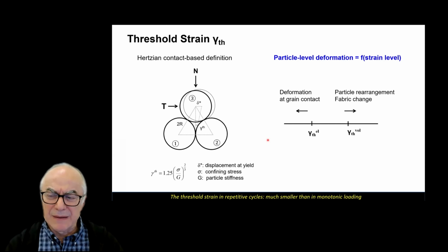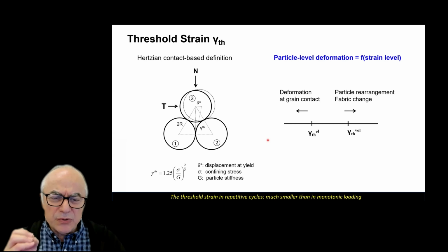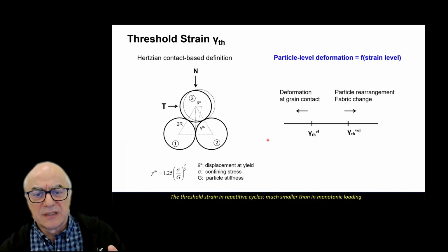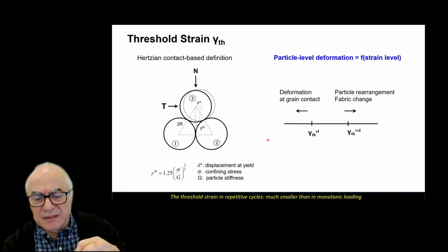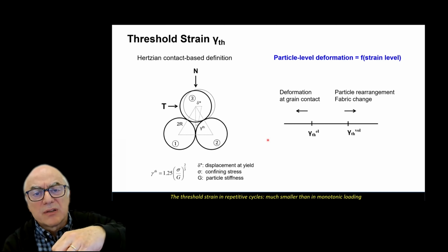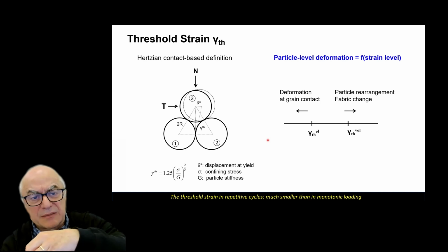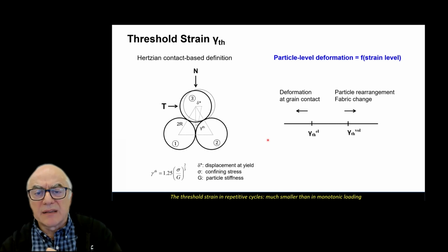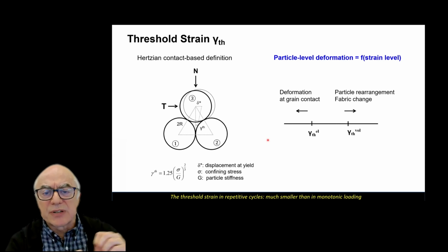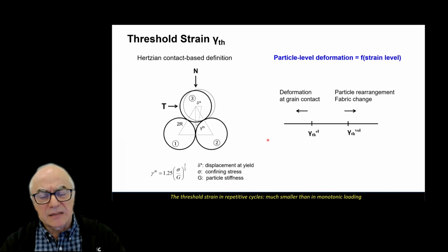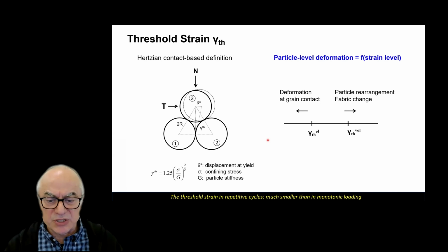on the material. It gets to a point that when you do the calculations, it appears that the relative displacement between 2 grains is smaller than 1 angstrom. And you say, well, but there has to be about 1 angstrom displacement in order to break bonds to cause frictional displacement, shear displacement. So what is actually taking place is not every particle moving relative to every particle. It appears that bunches of particles are gradually moving relative to each other.